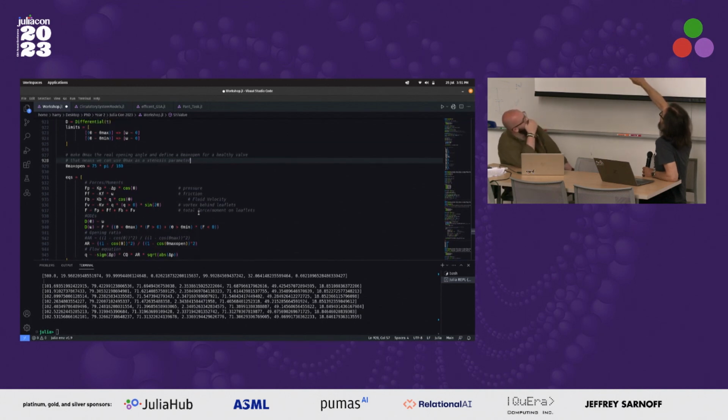And next, you calculate the area ratio, which is just this cosine squared equation, and then we have the Q equation, which takes the coefficient, the area ratio, and the square root of delta P into that calculation of the flow rate. So the tricky bit for this valve is that one additional second order differential equation, which we've reduced in order by defining omega, into two differential equations, and we had to introduce limits.